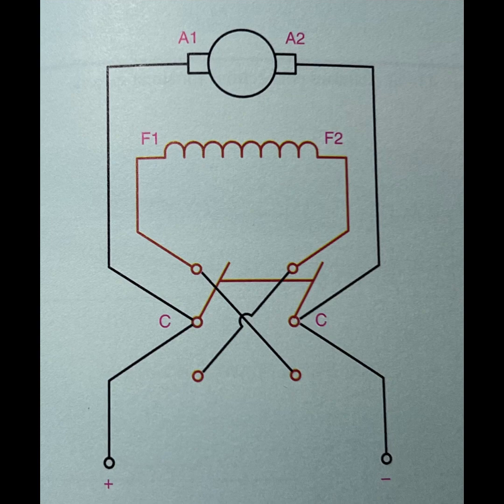When the ohm meter is connected to the series field and the motor shaft is turned, the ohm meter reading will not be affected. When the ohm meter is connected to the armature winding and the motor shaft is turned, the reading will become erratic as the brushes make and break contact with different commutator segments.